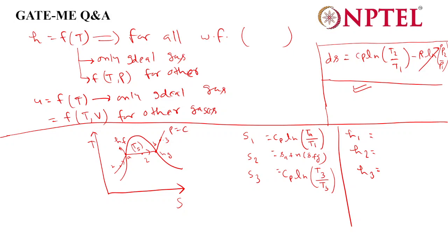But actually in state 1 it is in liquid state, no, sir? Yes, here Cp would be different: here Cp would be of liquid, and here Cp for the gas. And this equation is valid only for gases, but it will come the same. Because what would be the Q from here to here? Entropy is dq by T, and dq is Cp dT, so Cp dT by T, and then we simply integrate and the same equation will come. This is for liquids. For liquids this equation works anyhow, even if pressure is varying.